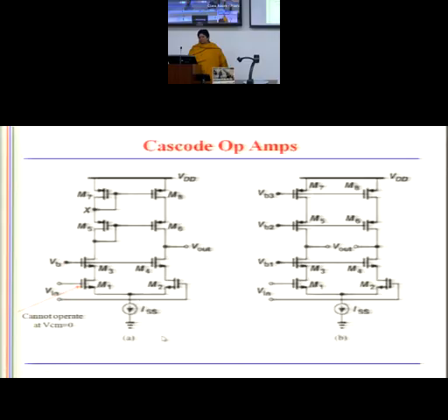And here you have the ISS. This is my source coupled node. This is a single-ended output. So what type of mirror are you using? Cascode current mirror. It's a cascode current mirror. If you have a fully differential topology, you will not have a mirror arrangement.